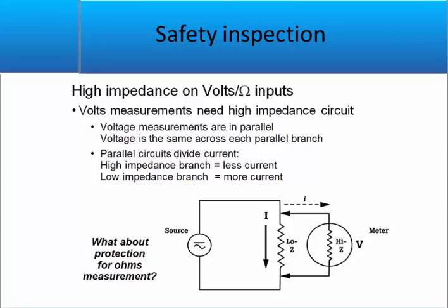In other words, make sure that the leads are intact prior to checking, because if you're using it to check voltage, you don't want a false indication that there is no voltage across it. Then check the voltage again, and good practice is to recheck the meter again to make sure that it is still functional.